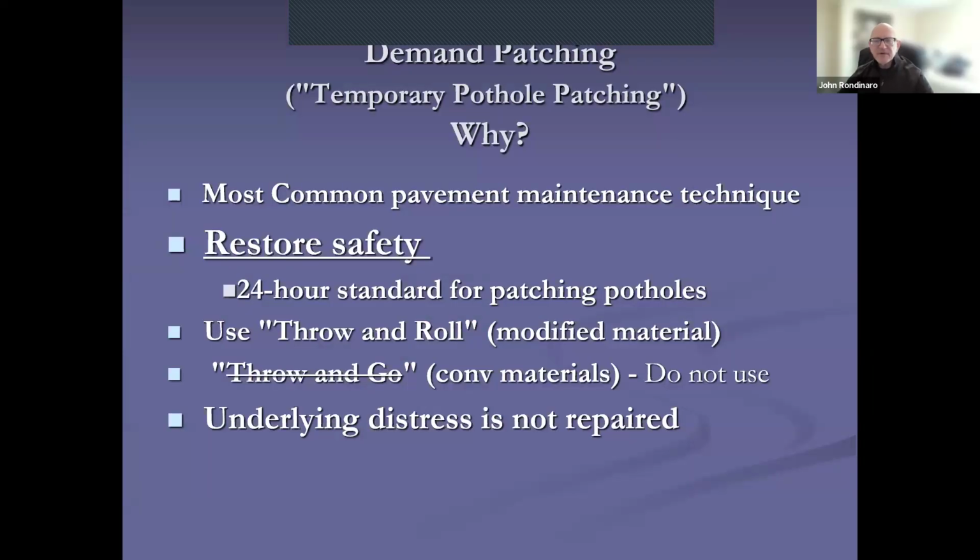It is our most common pavement maintenance technique. We're doing it to restore safety. In some cases, we've established 24-hour standards for patching potholes in different jurisdictions. The key here is that we want to be using what is called the throw and roll technique, using a modified patching material. In the old days, we were using the throw and go with conventional materials. It really doesn't work. And in all cases, the underlying distress is not repaired.